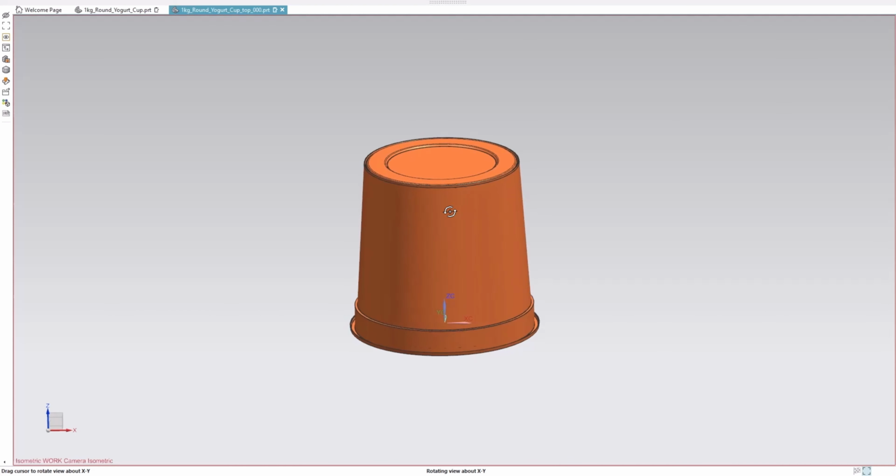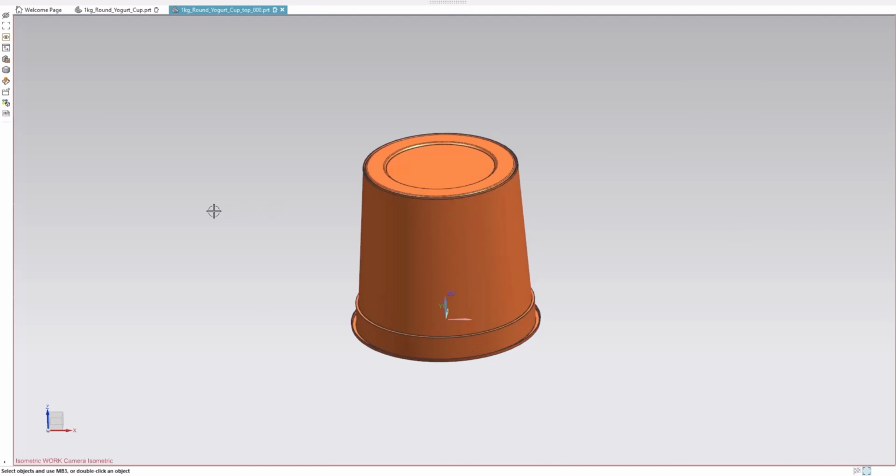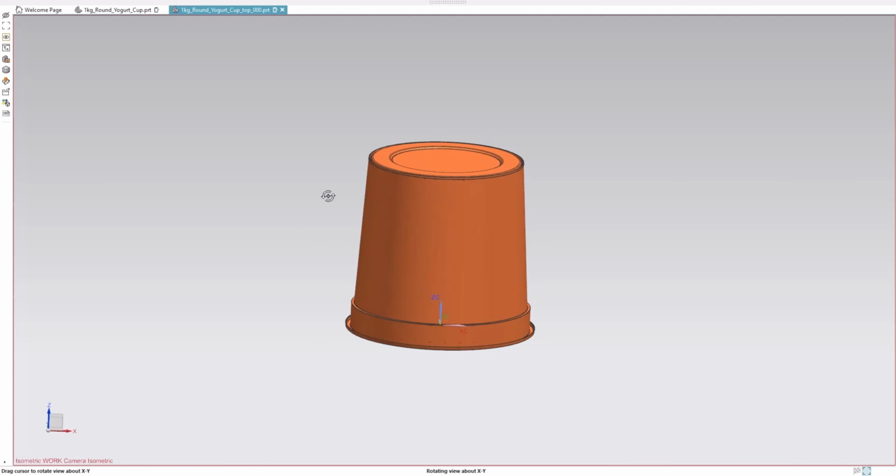I explained shrinkage in the previous video, but let me summarize briefly. When plastics are hot, this is not actually unique to plastics. It exists in steel, metal, and many other raw materials. It exists in plastic too. When it cools down, it shrinks. We call these shrinking margins shrinkage. In plastic injection molds, this margin is applied in its large, that is, its hot state, so that when it cools, it comes down to the original dimensions we want.